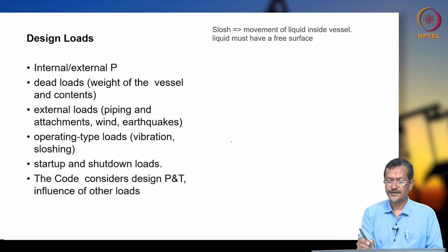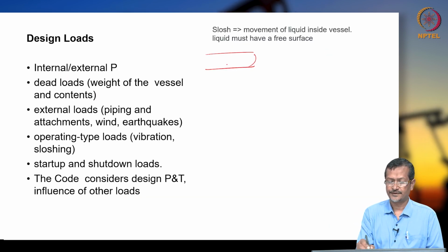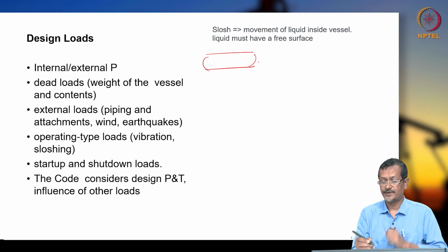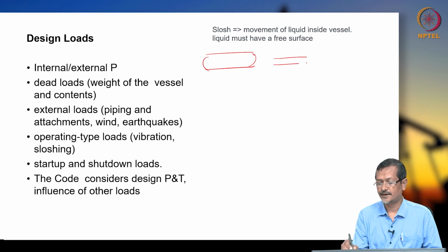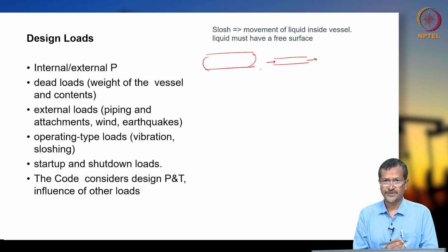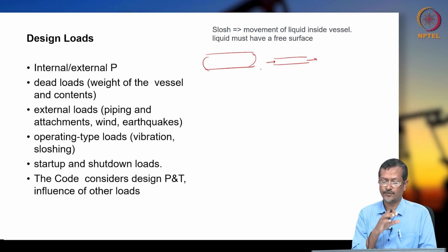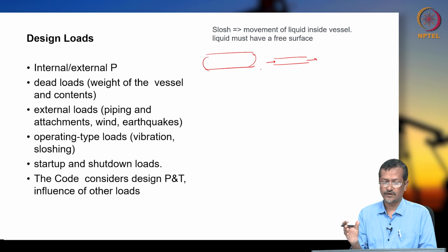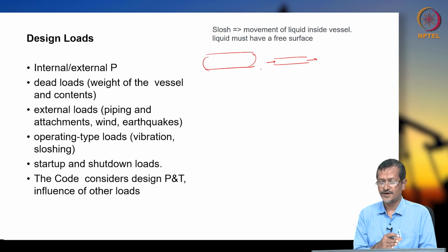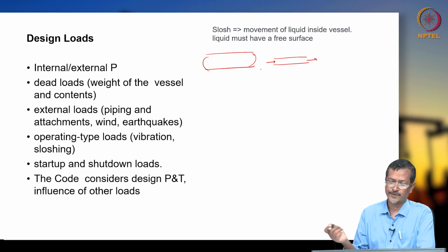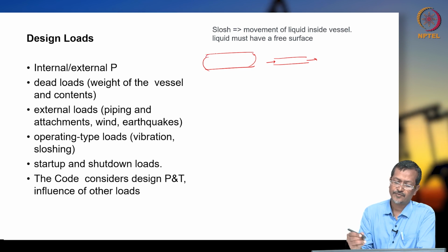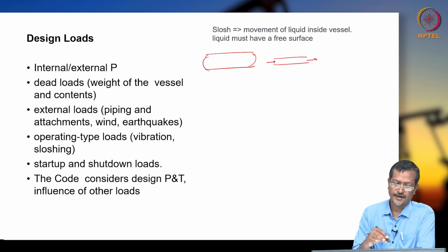So whenever you are designing a pressure vessel, okay, vertical or horizontal, maybe it will be a separator, it may be a boiler, it may be a pipeline. Okay, a high pressure pipeline also, pipeline connecting two separators, or pipeline transporting fluid or crude oil from one country to another country, cross country pipeline, gas pipeline. In that case you have to check internal and external pressure.